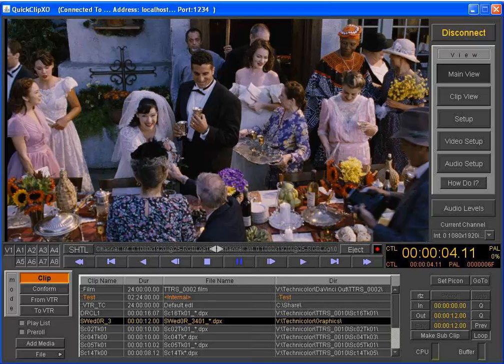The shuttle mode is like the jog mode, except the speed range is from 10 times play to -10 times play. Clicking and holding the left mouse button anywhere in the slider area will allow you to vary the speed. Releasing the mouse will cause the playback to pause. The VAR mode is designed for constant off-speed playback. Clicking the left mouse button in the slider area will start the playback between -100 and 200% of play speed. Releasing the mouse will cause the playback to continue playing at that speed.